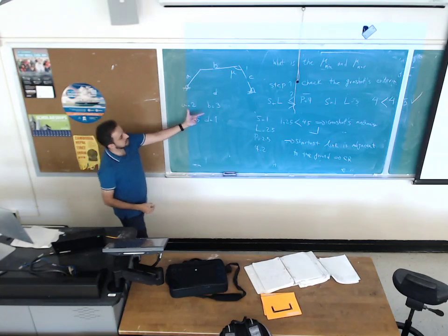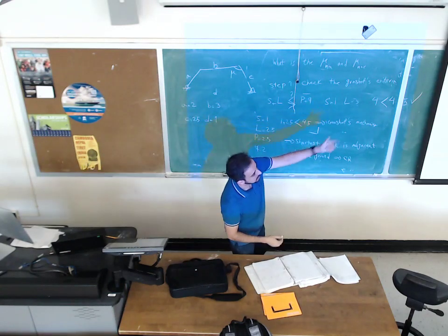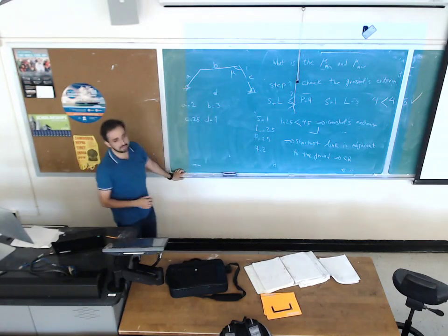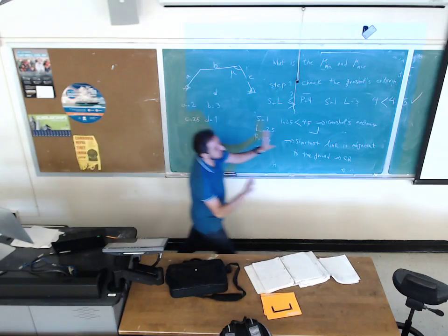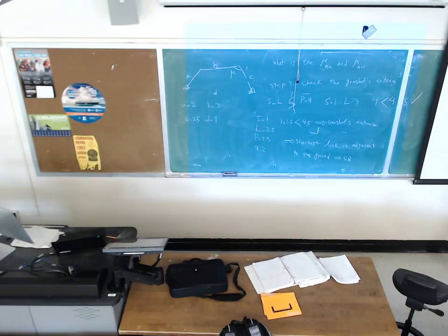So the same thing, just plugging the numbers there and solving for minimum and maximum transmission angle. If I change the input to this one, this angle is going to be the transmission angle. You should change these numbers correspondingly.